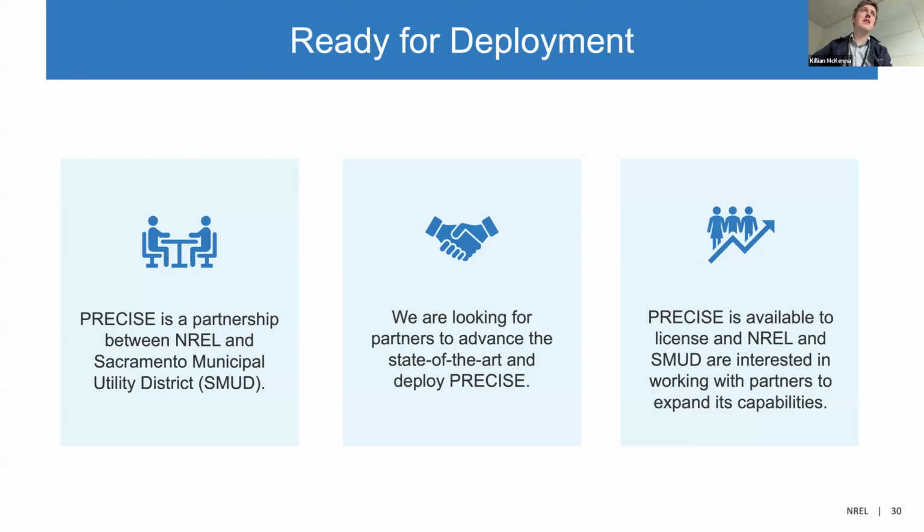Yeah, so I don't know whether the question is referring to distributed systems or bulk systems, bulk interconnection, because those are quite different processes. But I would say for distributed, a lot of utilities are still using screens similar to those found in FERC's SGIP, the small generation interconnection procedures.